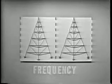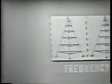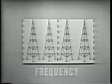Or two, to narrow the frequency bandwidth required for each radio signal so that more frequency space would be available for additional stations. The engineers' efforts to accomplish one or the other of these objectives has resulted in a more efficient communications system. It's called single sideband, and it's described as a technique of selecting and transmitting only a portion of the frequencies of the conventional AM waveform. Now, before we continue with single sideband, let's take a look at AM.